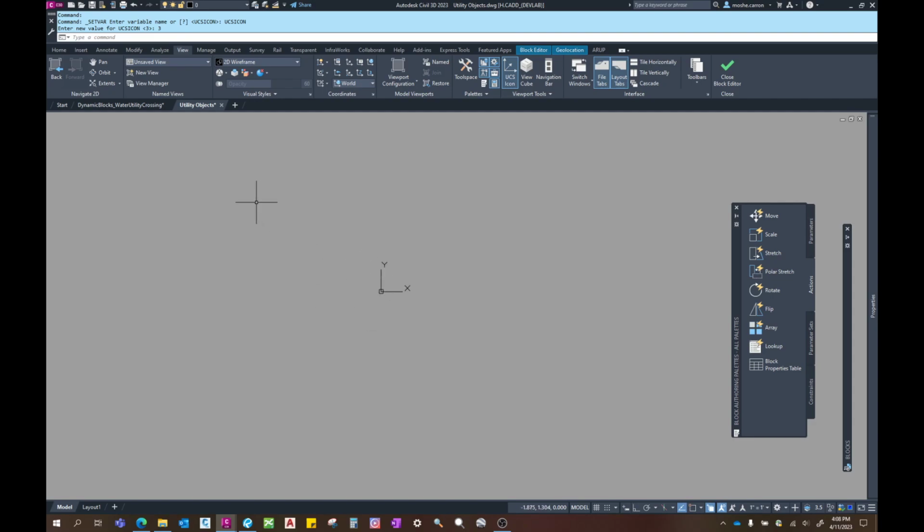So let's begin by drawing that polyline that we snapped to the underside of the crossing pipe. So I'll do polyline, spacebar, press 0,0 as shown on my command ribbon, press spacebar, and as you can see, it has snapped to the origin. I'll then turn on my ortho snaps, type in a generic 1, and press spacebar. So now I have a 1 foot long polyline snapping to the origin. I'll then extend it by 1 foot. So now I have 1 foot on either side, and that gives me a starting base from which to create my